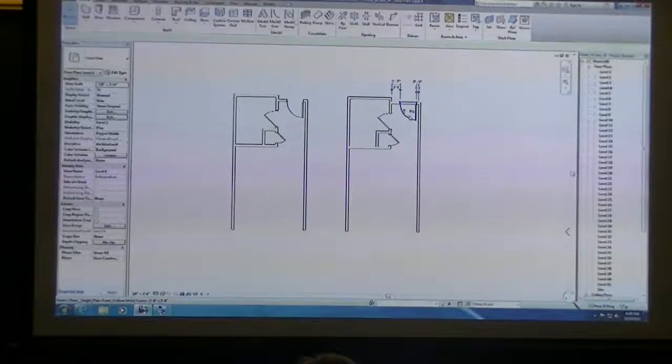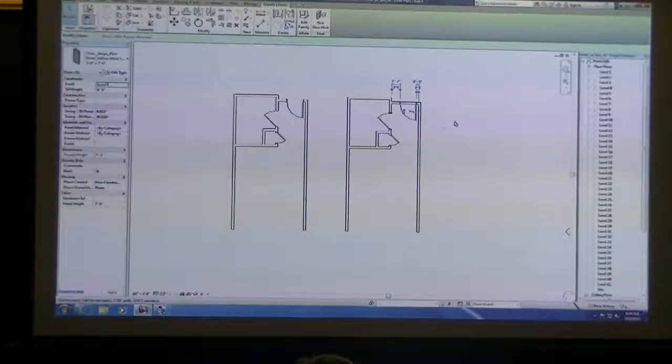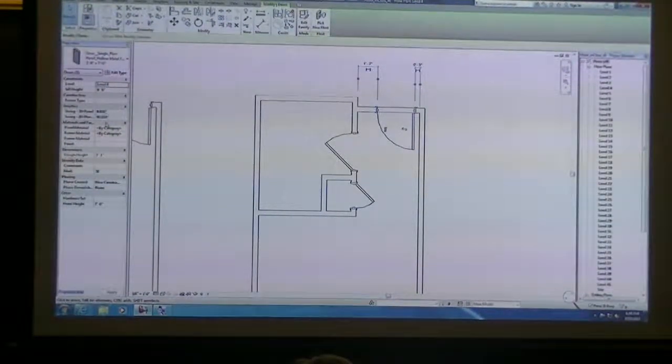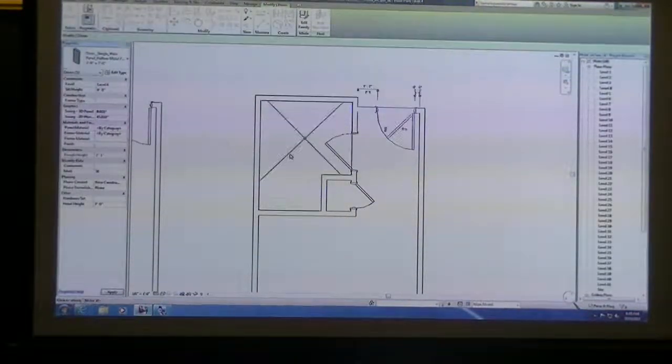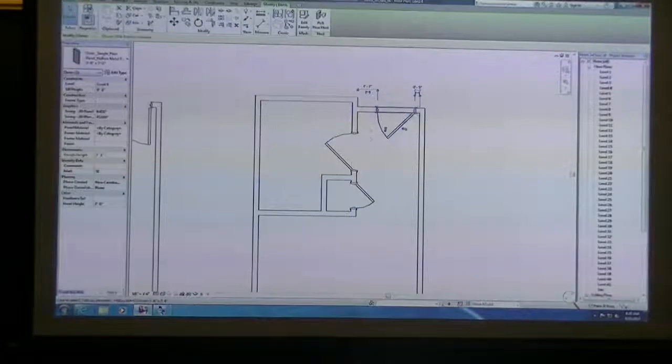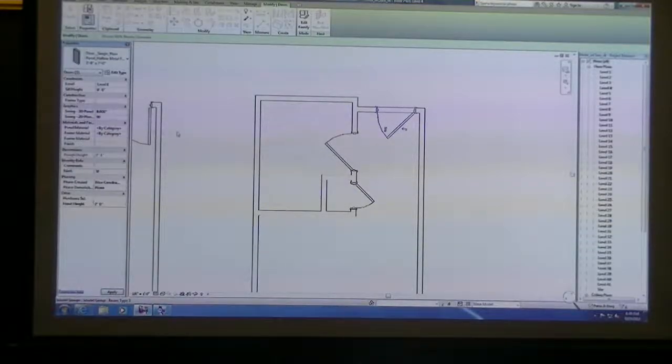So a couple other things with the doors that we're actually using. I went over also how these doors are set up where there's a certain set of parameters. Right now the default is for the door swing to be at 90 degrees. You can see the swing in 2D plan, and there's a swing 3D panel. I could change that to 45 if I wanted. If you start having a lot of door overlap, you can 45 your door angles or swings.